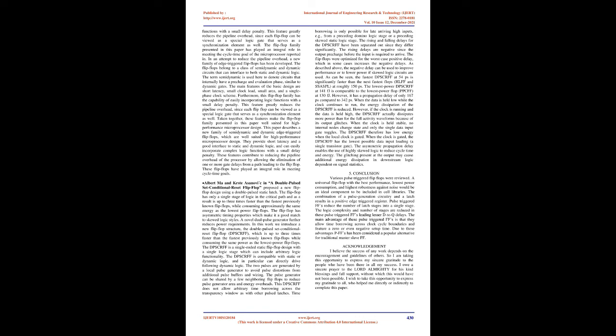Furthermore, the flip-flop family has the capability of easily incorporating logic functions with a small delay penalty. This feature greatly reduces the pipeline overhead, since each flip-flop can be viewed as a special logic gate that serves as a synchronization element as well. The flip-flop family presented in this paper has played an integral role in meeting the cycle time goal of the microprocessor reported. In an attempt to reduce the pipeline overhead,